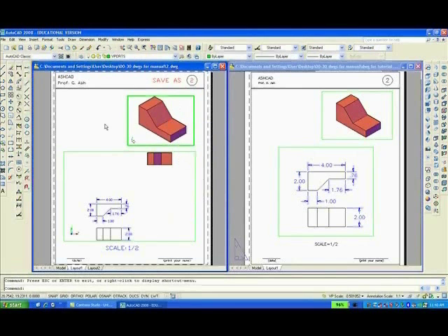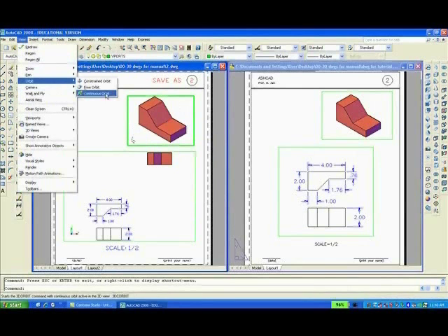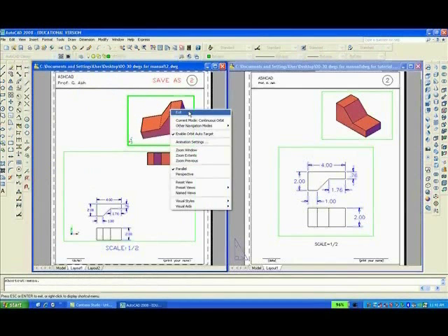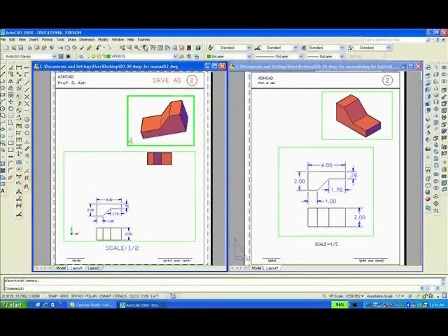Double click outside to get into paper space. On the other hand, remember, as we did before, you can go to View, Orbit, Continuous Orbit, or Fixed Orbit, whatever, and you can change this thing to do all kinds of tricks for yourself. Right click, Exit, Zoom Previous.